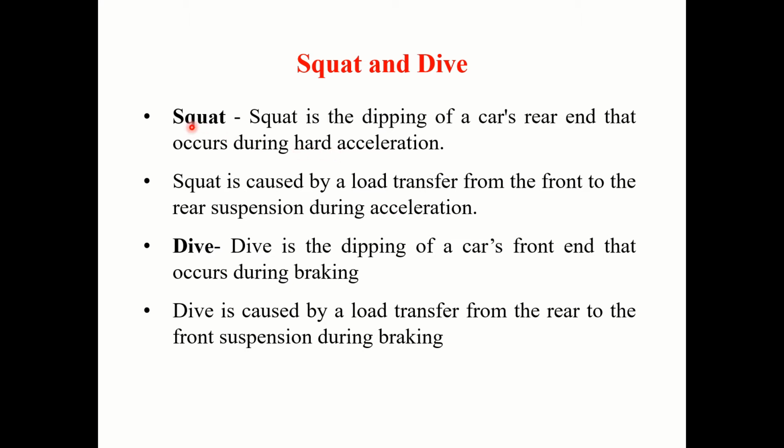This is what we call squat. Squat is the dipping of a car's rear end that occurs during hard acceleration. So it is caused by load transfer from the front to the rear suspension during acceleration.